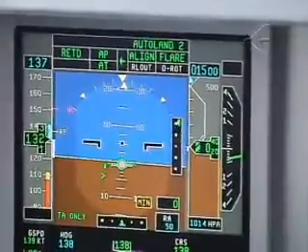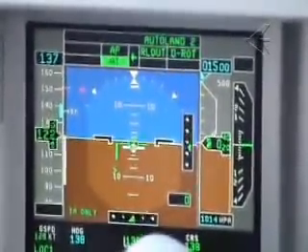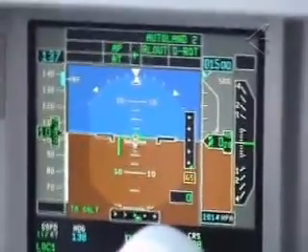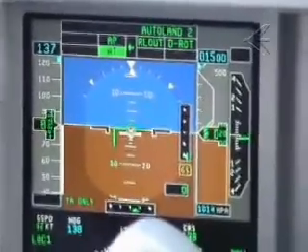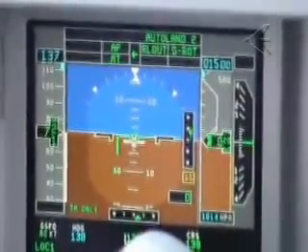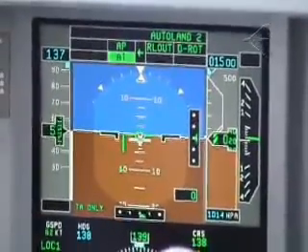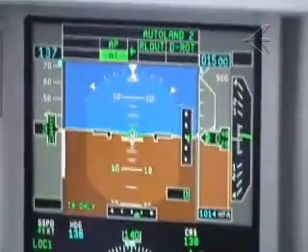On the Autoland 2, landing rollout through a safe taxi speed is controlled by the autopilot. Autobrake will decelerate the airplane, and reverse thrust is available for manual application. If not disengaged before, autopilot will automatically disengage at 12 knots of ground speed with a corresponding visual and aural warning for the autopilot disconnection.